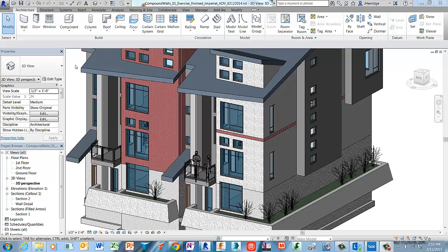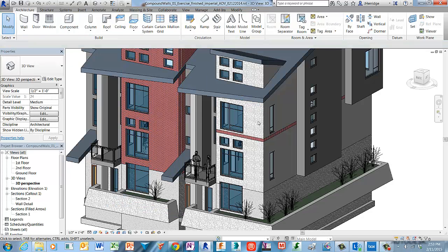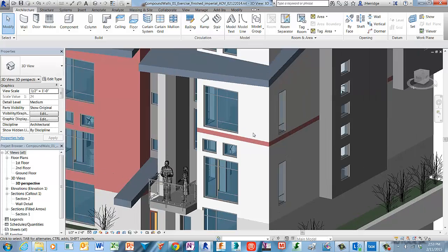In the previous wall lessons, we looked at creating simple multi-material wall types with materials that have a constant thickness in the vertical plane. In this exercise, we will expand on this knowledge by creating multi-materials stacked in the same plane or column of space. We will use the split region tool, which allows us to subdivide that column of space into multiple segments and then assign those to different material layers.